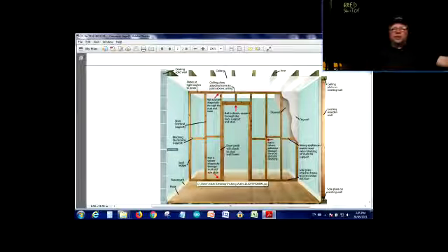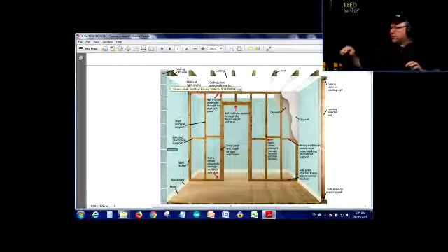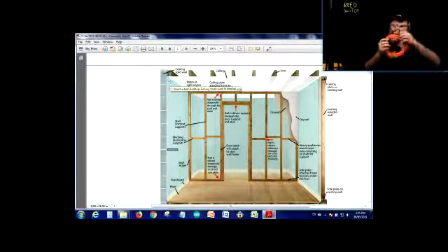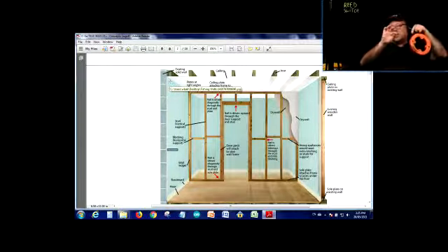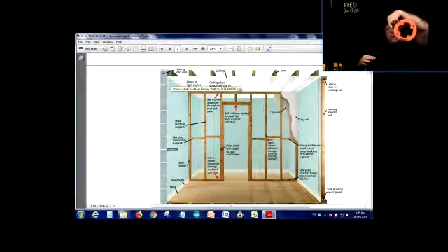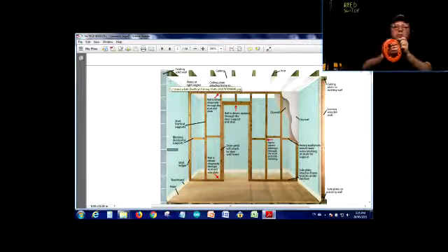If you know that they are going there, then yeah. But sometimes, if you can, push the fish line in there. And do I have a fish line here? Yes, I do have a fish line. You can push it in there and see how far it goes, and pull it out and see, okay, it goes from here to here. So maybe there's some obstruction there, so we won't be able to pull the wire right to the very bottom. Yeah, that's as far as that goes.